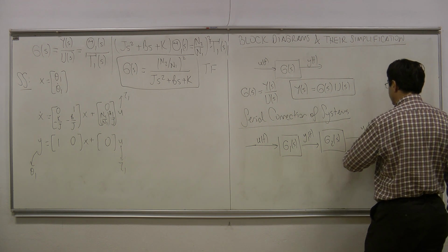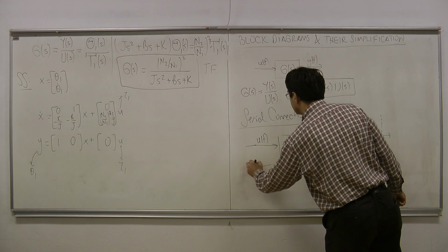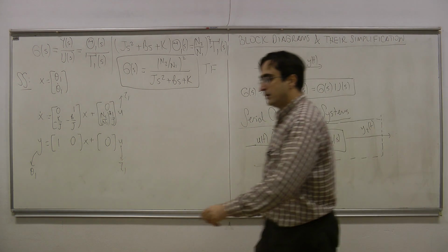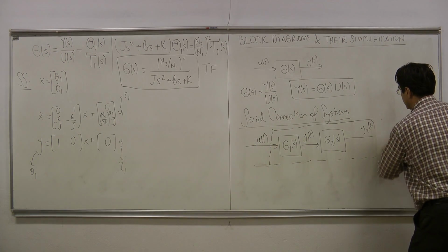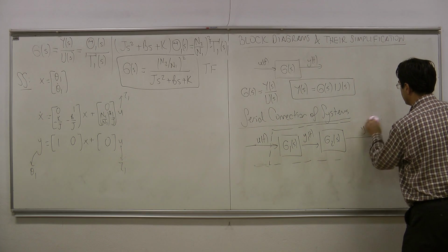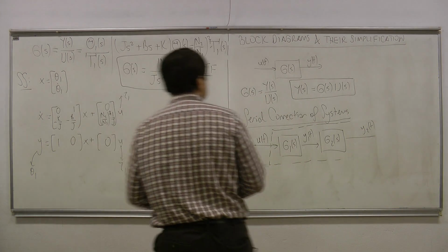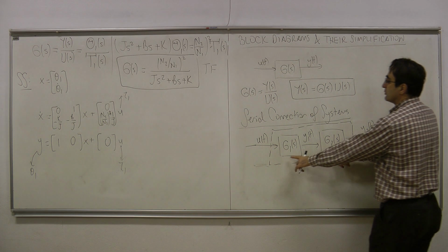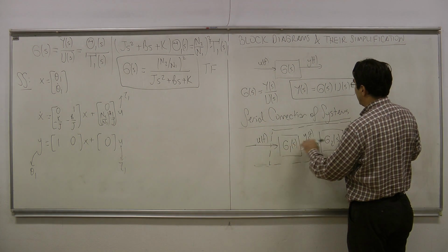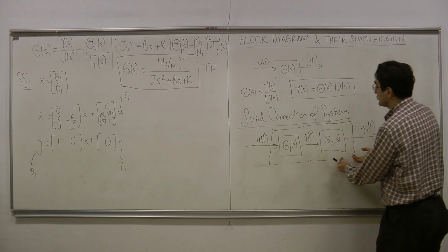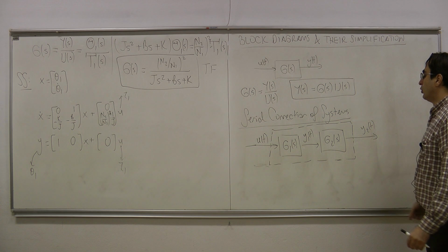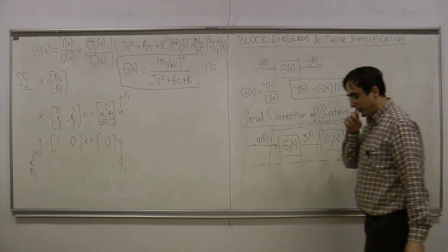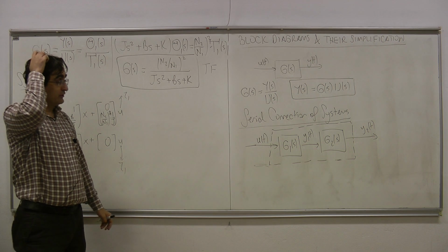Suppose that I would like to represent this system with a single block. Okay? This single block would be looking, maybe I didn't draw it in a nice way. I should have drawn it like this. Sorry. So this y2 is remaining there. I am actually cutting this block here. So suppose that I would like to think about these two systems as a connected system, and I am wondering about what the transfer function of the overall system is that I get by connecting these two systems in this topology. Okay? Let us try to derive that.